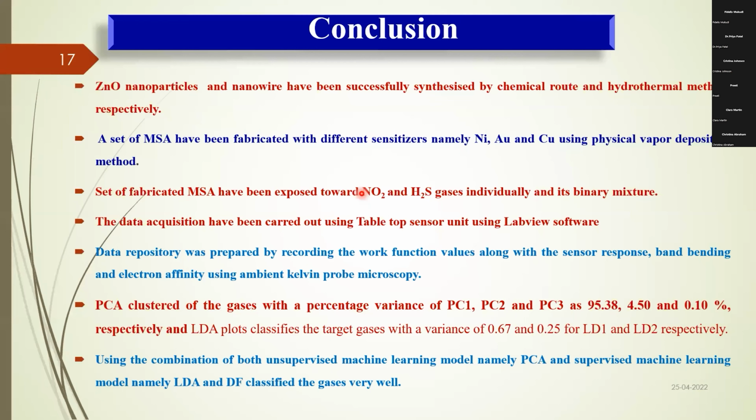And here is my conclusion. Zinc oxide nanoparticles and nanowires have been successfully synthesized by chemical route and hydrothermal method respectively. A set of multiple sensors have been fabricated with different sensitizers, namely nickel, gold, and copper, using physical vapor deposition.